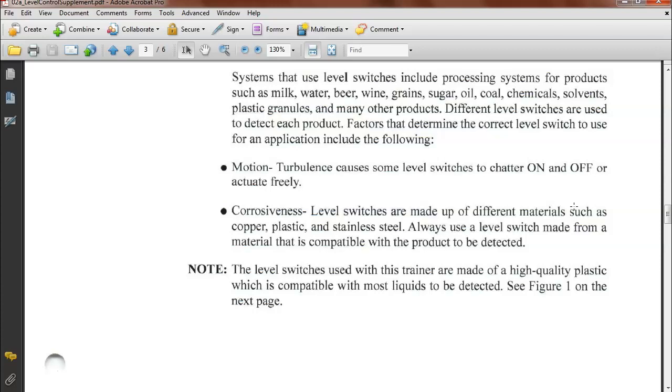Do you know technically what a cable is? It usually has two or more wires inside a common jacket, and the conductors will have insulators, but that piece of plastic they wrap around is the jacket. That jacket is not in there as an insulator. It's there to determine what environment that cable can run in. Right? That makes sense.